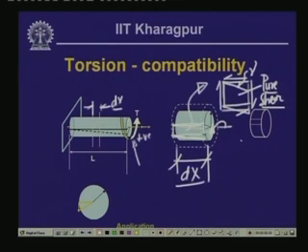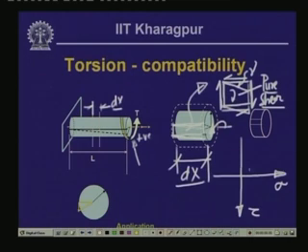Now, if you remember, if we plot this state of stress in the Mohr circle, this is the sigma axis and this is the tau axis. Now, here we have negative, because this is clockwise movement by this particular shear on this face. So, as per our notation, this is a negative shear which is plotted on the top side of the Mohr diagram, and for the other side we have a positive value which is plotted over here. So, this is the value of tau, and if we plot it as a circle, this is the center, and if we plot the circle,